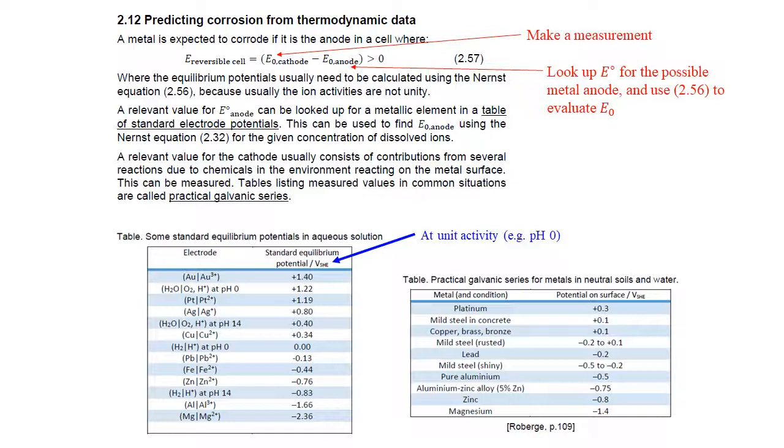And this comes about because zinc dissolution is a fairly significant process on zinc metal, and other reactions like hydrogen ion discharge are not very strong. So the galvanic potential for zinc is close to the standard equilibrium potential for zinc. In comparison, on iron, and even more so on rusted iron, the mixed potential is quite a bit more positive than the metal dissolution equilibrium potential.